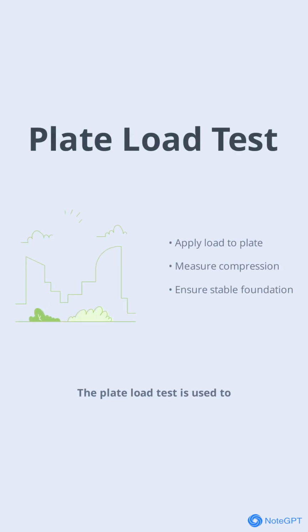The plate load test is used to determine the bearing capacity of the rock fill. By applying a load to a steel plate placed on the fill, engineers can measure how much the fill compresses under pressure. This information is essential for designing structures that will be built on top of the fill, ensuring they have a stable foundation.